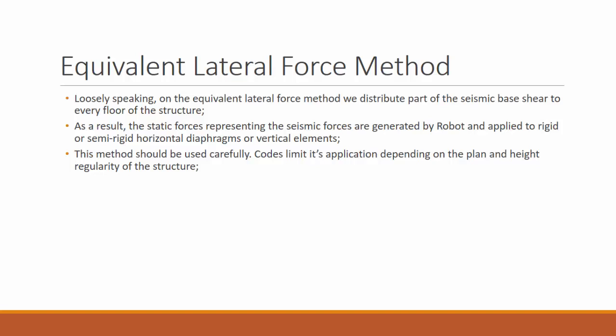So if you have a very weird and complex structure, you may need to do a modal analysis and spectral seismic calculation. You may do this if you have a regular plan and regular height structure, with nothing crazy, which is the case of our structure.